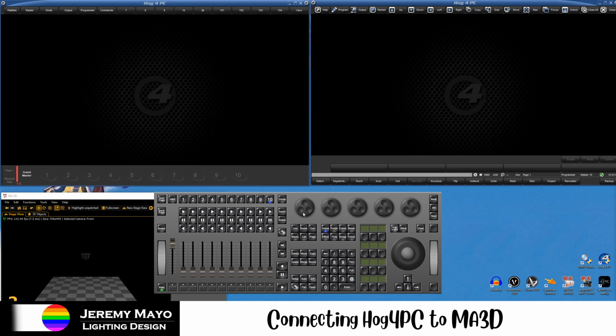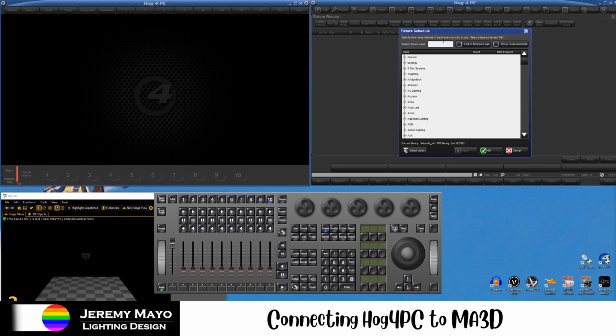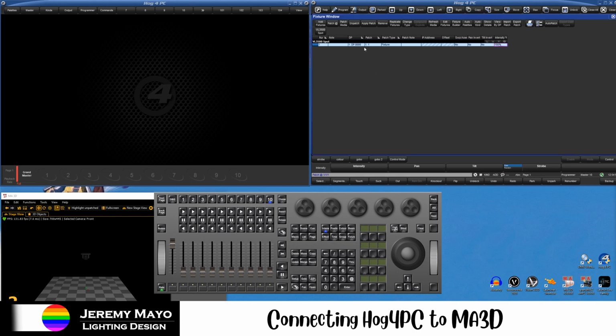Great, so now we have the software booted. The first thing I'm going to do is populate the patch the same exact way as it is in MA2. So I'm going to go to Setup, Patch, and again, I'll just add a Vari-Lite 3500 Spot. Did I add just one? Great. We're going to patch that to the only processor we currently have available. We should just have one DP8000. We're going to go ahead and hit OK and patch 1 to 1.